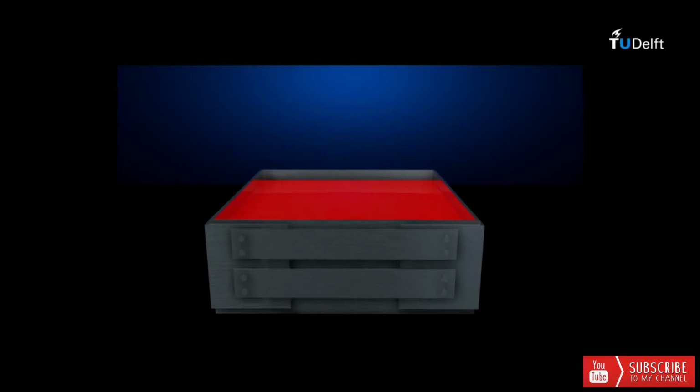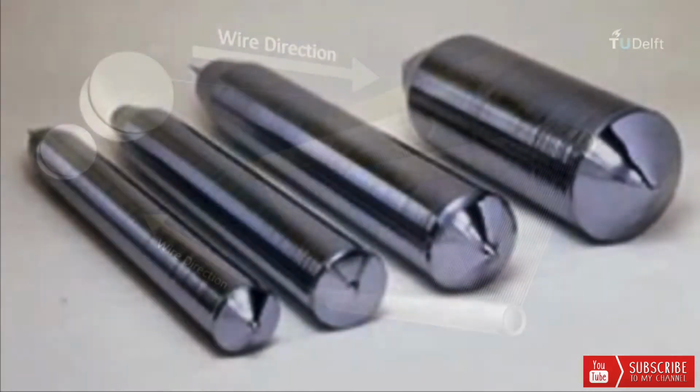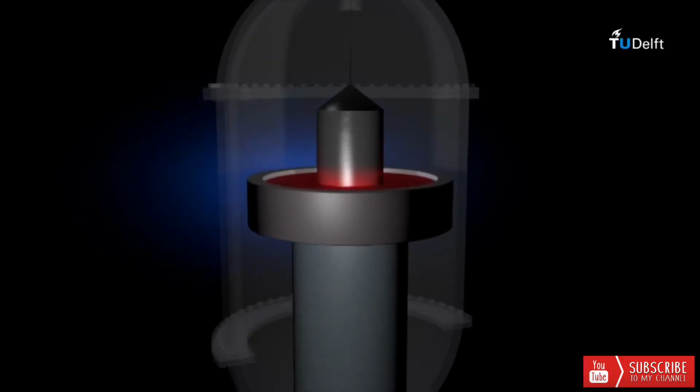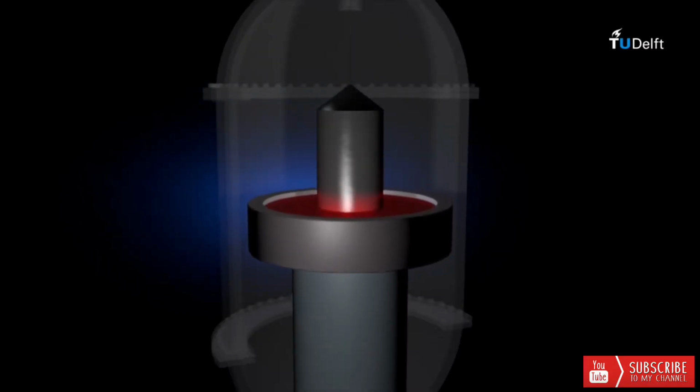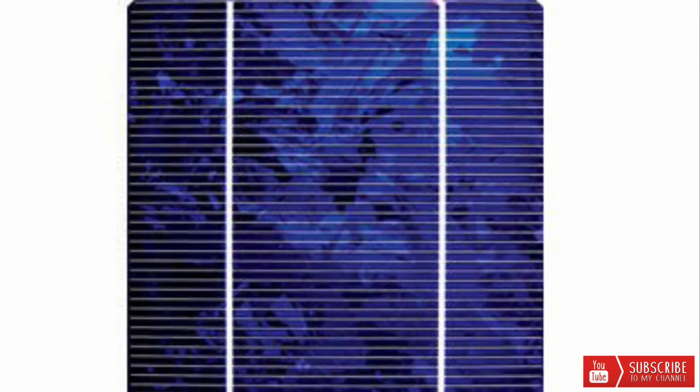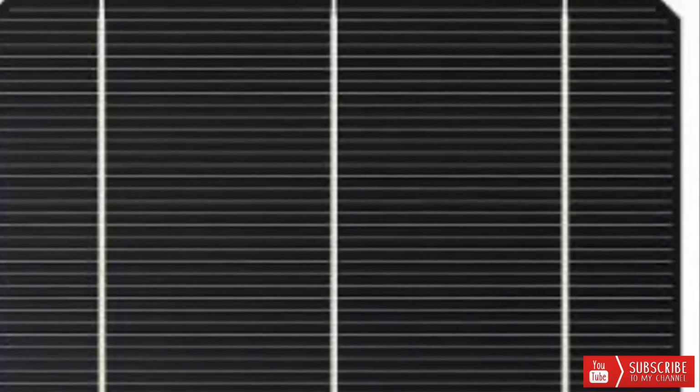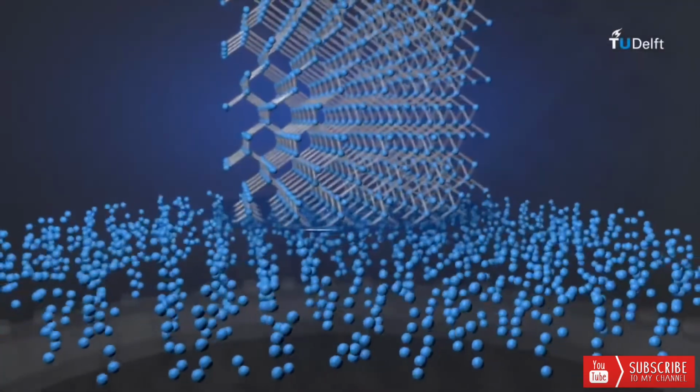So silicon crystals have different structures and orientations. Monocrystalline silicon ingot gives us monocrystalline solar cells, whereas polycrystalline ingot gives polycrystalline solar cells. Or in other words, monocrystalline cells are made out of a single crystal of silicon, whereas polycrystalline solar cells from several crystals of silicon melted together. You can recognize them by the shattered glass look given by the different silicon crystals. The higher efficiency of monocrystalline solar cells can be attributed to the uniform structure of silicon atoms inside monocrystalline silicon.